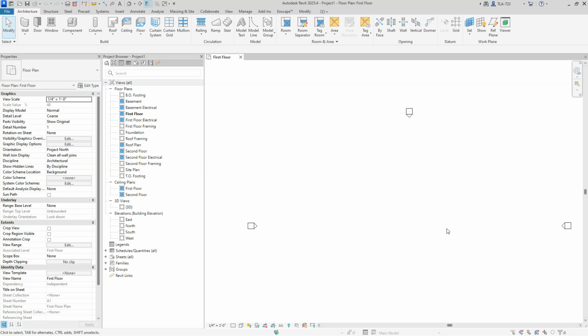We're going to be placing walls over the top of a CAD file, which, by the way, you need to download ahead of this lesson. So if you haven't already done that, go ahead and go out to the assignment, click on the CAD file. It's called house.dwg. Download that to a location that you'll be able to find it, because we're going to link that into a Revit project, and we're going to use that sort of as the background that we're going to trace over to create this house.